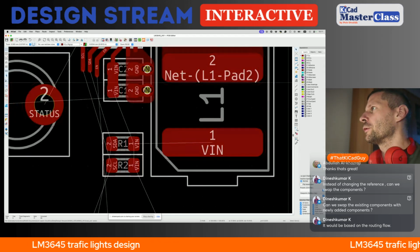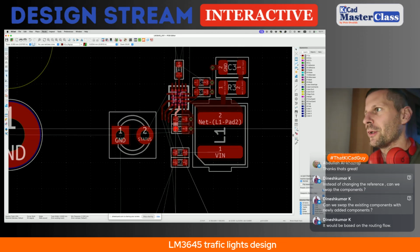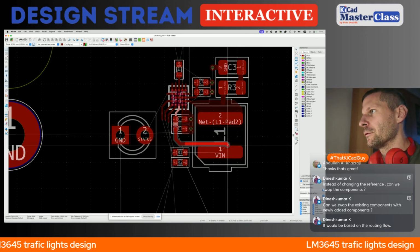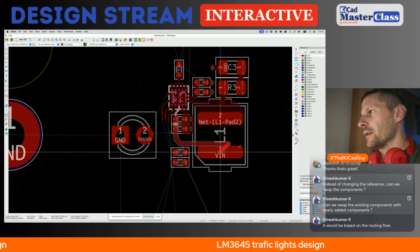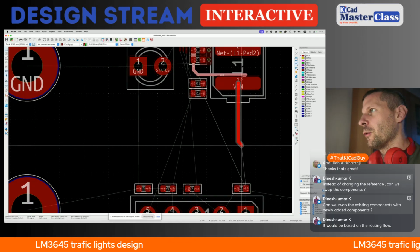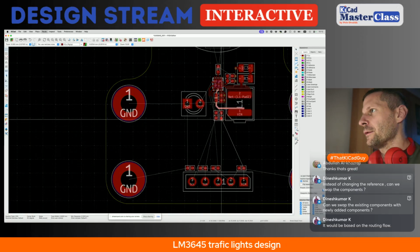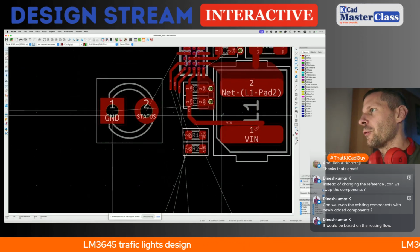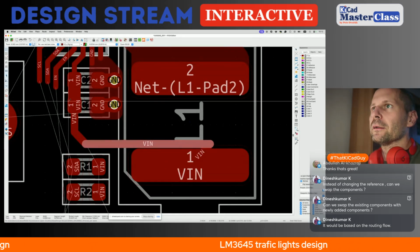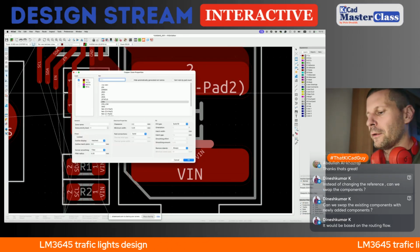And we need the input voltage polygon. Yeah, let me use this trick, like to project the shape of the polygon. It will be something like this here, and from here that can be only a track, and these components will be connected just by wire. Okay, so this will be our polygon, like from here.